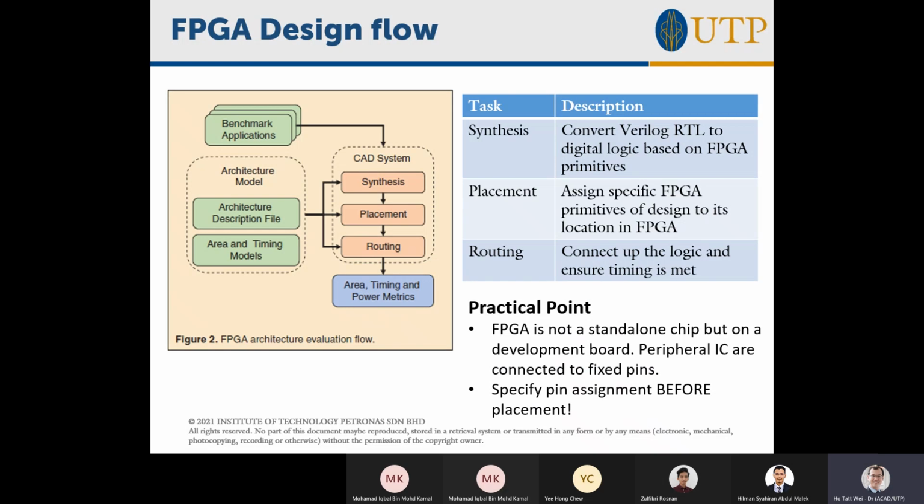So this is where you already have certain pins locked. If you want to access that device, or use that other device on the board, you need to actually connect to those pins. Because of that constraint, when you're programming the FPGA, you have to watch out for those pins that you need to use, that are already connected on the board to something.